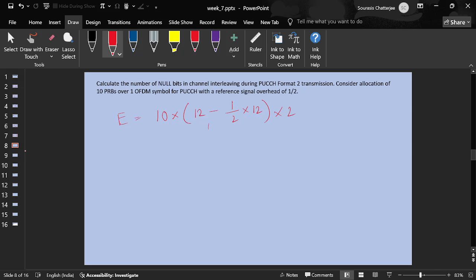The control information carried by PUCCH, we use whatever modulation scheme is in PUCCH. Okay, so you are saying when I have nothing to transmit in the uplink except control information, then I am using PUCCH, and in that case I am going to use QPSK.